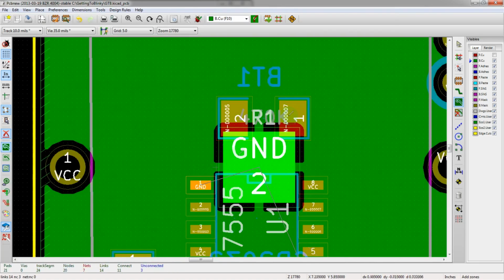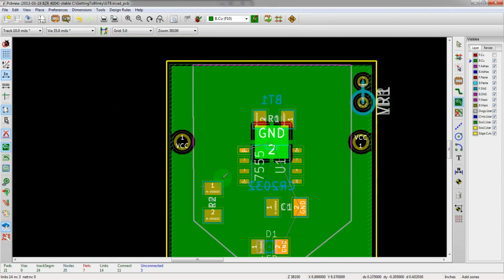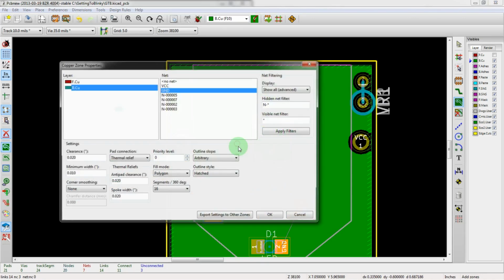Now you can see it connected at this big ground pad here, so it looks like it's going to be all copper, and it is in the actual copper layer. It's going to look like all copper. However, the only thing that's going to be exposed is actually right here on the ground pad. That's the only thing that will actually be showing through. So when you want to connect up a battery, it'll actually touch there. It'll touch that copper.